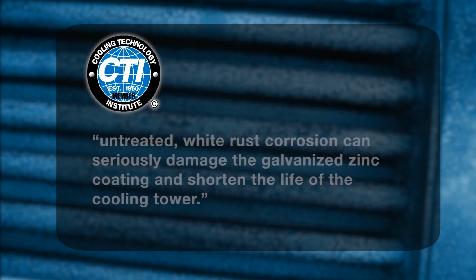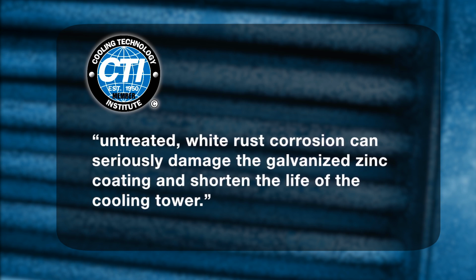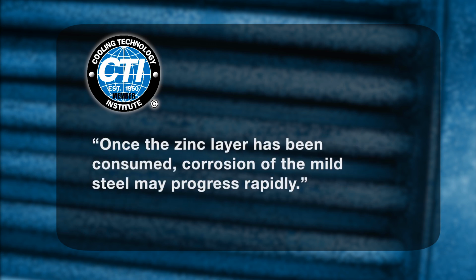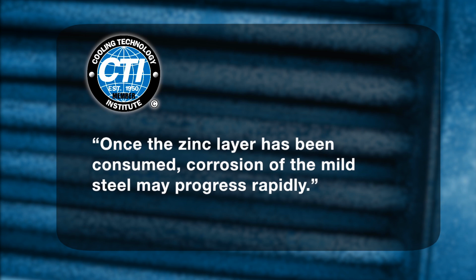Meanwhile, our friends at the Cooling Technology Institute stated in their 1994 publication on the topic that untreated white rust corrosion can seriously damage the galvanized zinc coating and shorten the life of the cooling tower. Once the zinc layer has been consumed, corrosion of the mild steel may progress rapidly. So now we've established that white rust has become a problem for new galvanized steel in the evaporative cooling industry. And to prevent it from causing serious damage, the equipment needs to be protected.